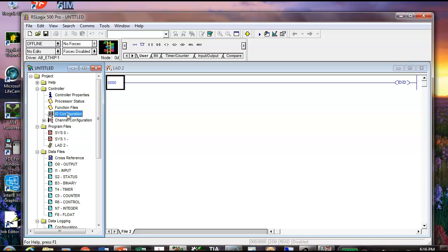You'd have to say, okay, in slot 1. So if I was dealing with that PLC, and I might hook one up before the end of the term and show you what we have to go through. On those, you have to specify the slot. First of all, you have to specify the size rack you have. So we'd have to specify a 7-slot rack, and then we would have to say where we put these modules.